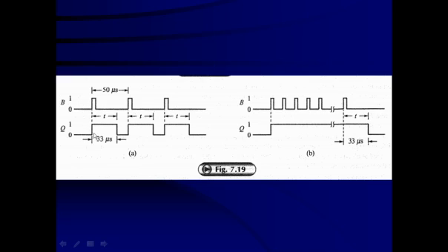So you can see that the pulse duration is going to be 33 microseconds and the clock pulses which are given are spaced by 50 microseconds. So before the second positive edge comes, you can see that it has already come into the stable state. So again it can be triggered here and again it will time out after 33 microseconds and it is ready to trigger for the third clock pulse. So on every positive transition, the circuit is going to be triggered and it will time out.